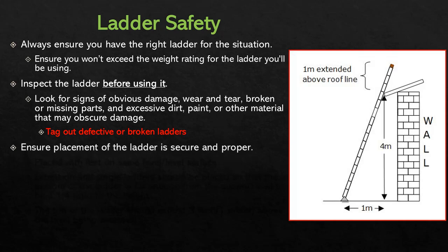Ensure the placement of the ladder is secure and proper. What this means is that the feet of a ladder, whether it's an extension ladder, or a step ladder, or even an A-frame ladder, need to be on the same level and on a level surface. There are some ladders that are specifically designed for uneven surfaces where the left side and the right side can be uneven, but most ladders are not designed for that. If you have them on uneven surfaces, the ladder is not going to be straight. And as you climb the ladder and get further from the ground, the chances of the ladder falling to the left or right and taking you with it are greatly increased.